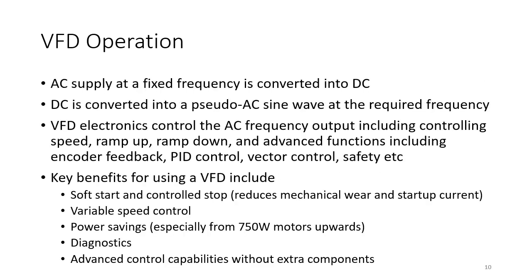So how does a VFD work? Well, we start off by having an AC supply coming in at a fixed frequency into the variable frequency drive itself. This AC supply comes from our main supply, and that's normally fixed by the power generator. Typically in Europe, that's 50 Hertz, plus or minus maybe half a Hertz or less. In the USA, you might see 60 Hertz. In other countries, they would typically use 50 or 60 Hertz, depending on the country.